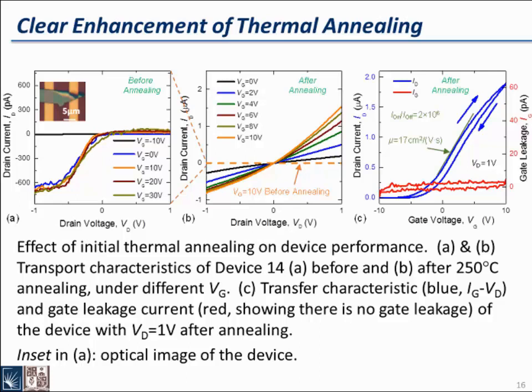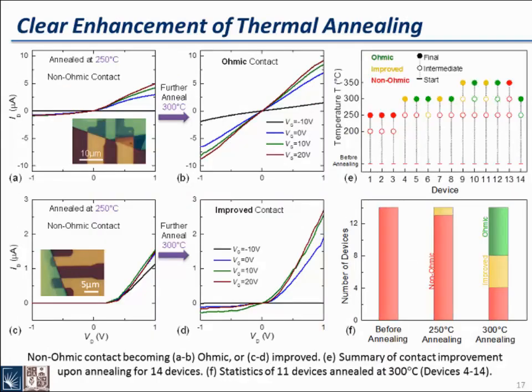Before annealing, the on current is very low. So this dashed curve is actually this. But after annealing, we can see the on current increase dramatically. And then through a lot of trials, we found that the dry transfer combined with post thermal annealing can enable very good ohmic contact for those electrodes. So we have done very significant study, like many generations of devices.